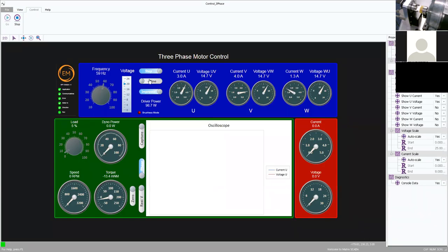Now, you can either have your outputs digital, so they're 120-degree phase shifted square waves, or you can have sinusoids, again at 120 degrees, or to really improve the system, you can use a system where we add third harmonics to the sinusoids, which produces a pretty perfect sinusoidal current inside the windings. If you don't do that, there's distortion on the windings. And so you can have access to control what kind of signal you're driving your system with. But in this particular case, I'm using a sinusoid, and I'm using the improved third harmonic sinusoid.